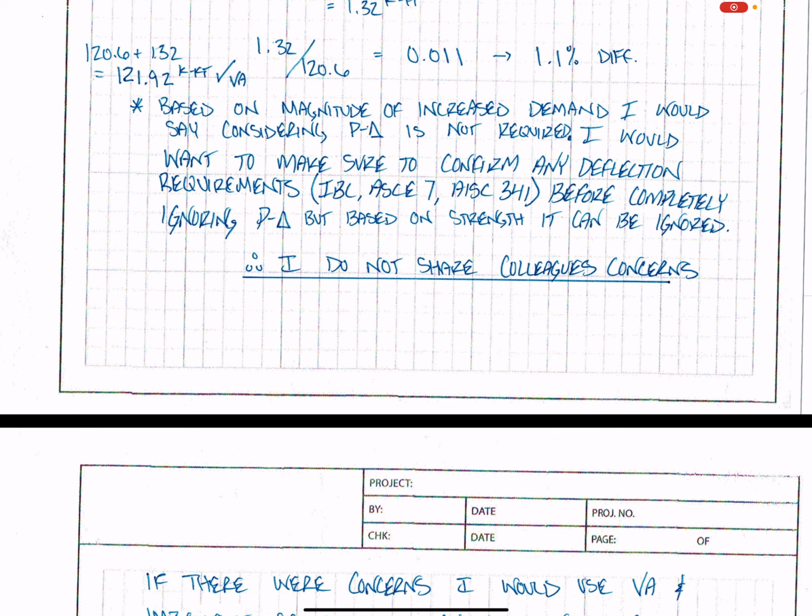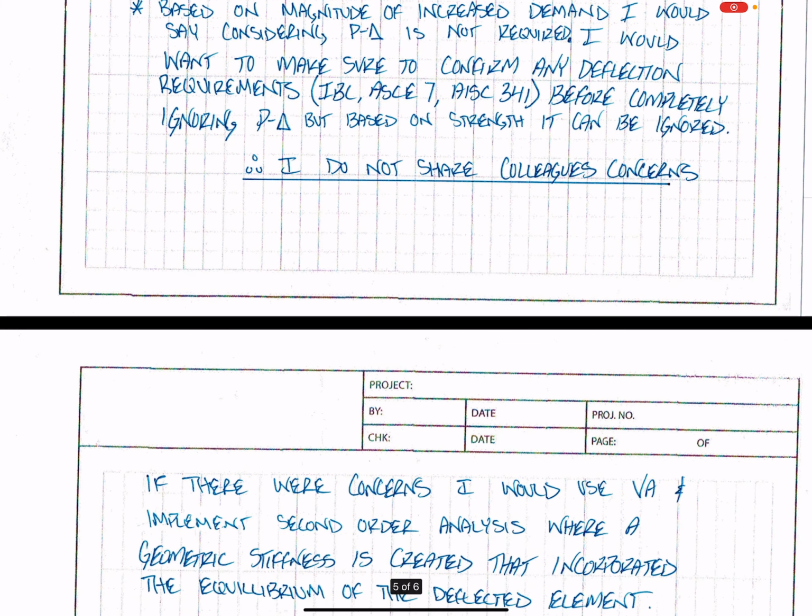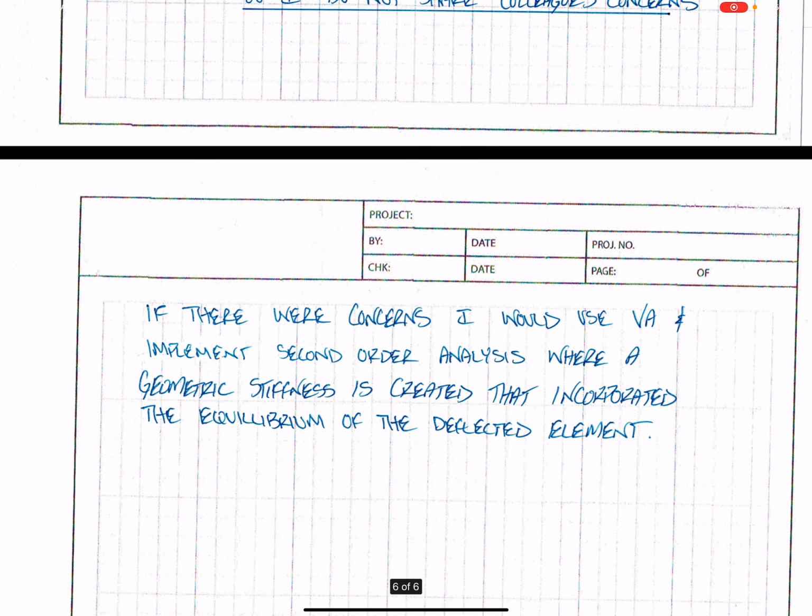But in some areas it might not be as easy, right? It might not be as small of an effect as it might be if we were looking at deflections and we were right on the edge of the tolerance, which ends up happening a lot of times when we're looking at flexurally dominated lateral systems like cantilever columns or moment frames, right? A lot of times they're really strong as hell, right? The strength is not a big issue, but it's the displacements that really govern what the design is, okay? Displacements because of P delta or because of serviceability? Serviceability usually, yep.